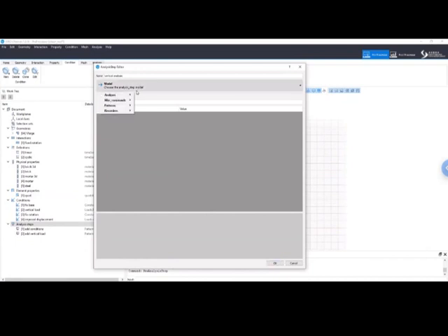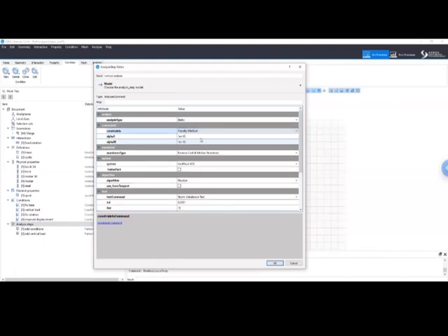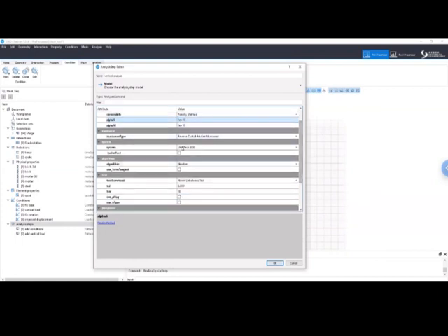We go under Model, Analysis, and Analysis Command. So the analysis here is static, even if we are doing a cyclic analysis, but it is still static. By default, the constraint handler is plain constraints. Unfortunately, we cannot use the plain constraint in this model because we are using an imposed displacement. So what we're going to use is the most general one, which is the penalty method. And we can leave the default values as this one, 1 to the power of 18. The number is fine, this one by default. Also, the default system is fine, the UMFPACK.